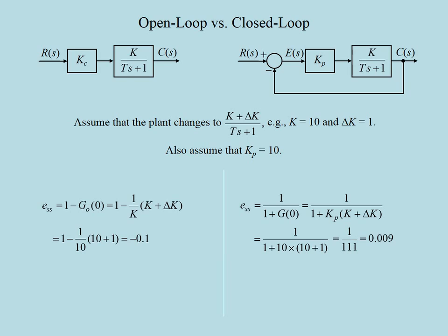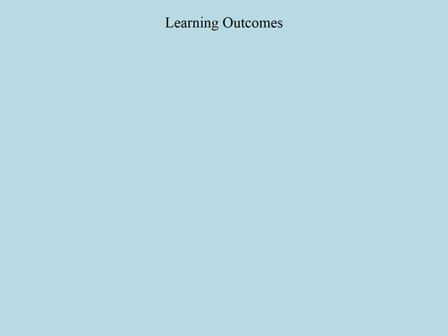That means the open loop controller may look like resulting in zero error ideally, but in real life, where you would almost never expect nominal values, the closed loop operation is much more robust against the changes or uncertainties in the plant. This is the end of our discussion of steady-state errors in unity feedback systems.